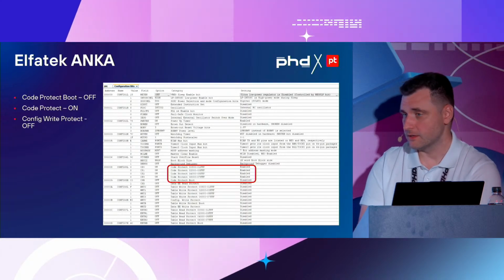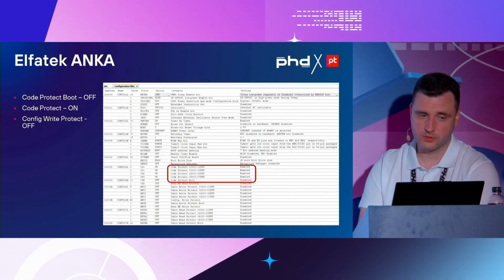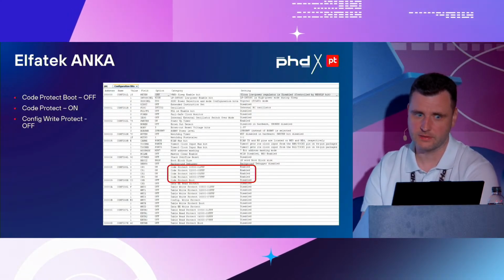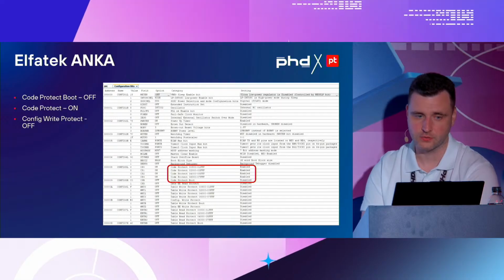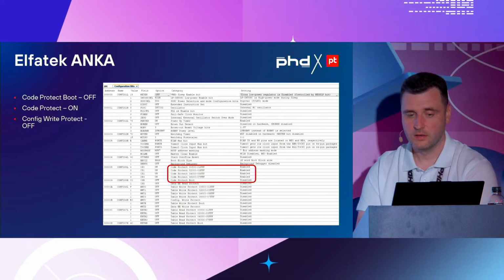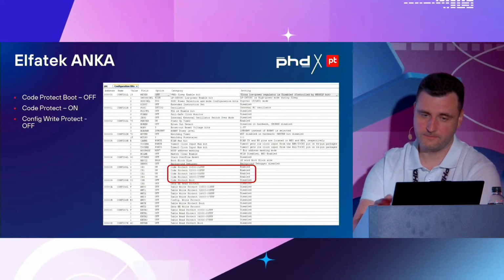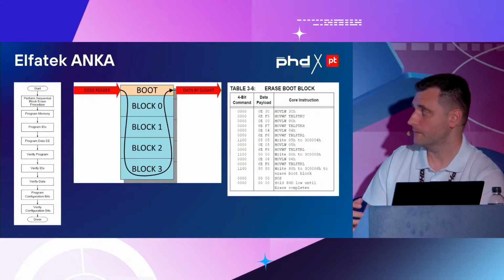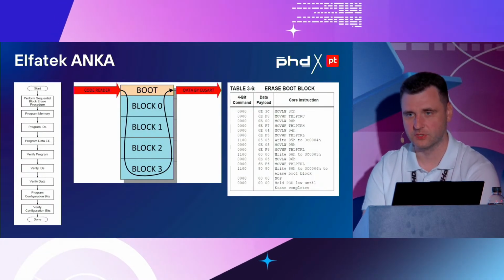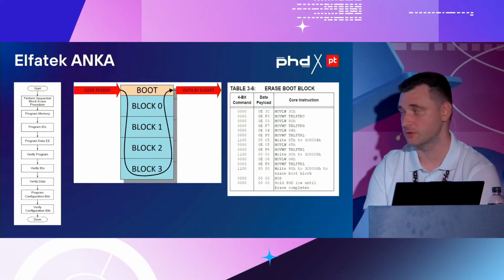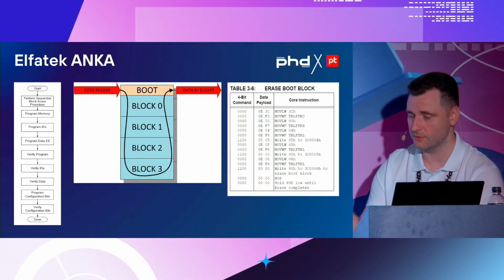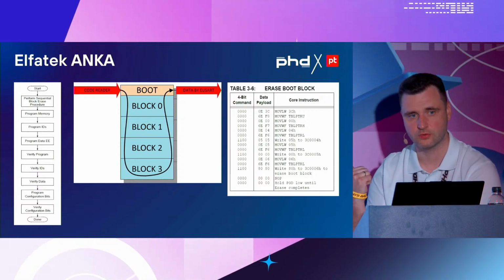And again, we remember that such an attack is quite well known, despite the fact that you can read only the content of BootBlock, about 2 kilobytes, and the rest of the code is not accessible because PIC operates with blocks of flash memory. But nevertheless, you can do the following. You erase BootBlock, scan it, then you make your own BootBlock that through UART will give you access to the other parts of the memory.